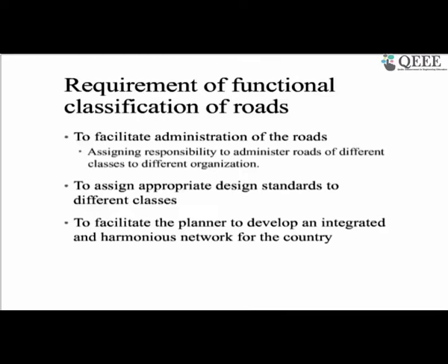The main goal of the expressway is higher speed, and to attain higher speed, as I told you, the access needs to be controlled. Along an expressway you won't find any parking or any dhaba or those types of accesses where people can stop. It is controlled through toll booths, so people can enter from one location and exit from another location. In between there are no entries and exits to the expressway system. So this is the primary differentiation.